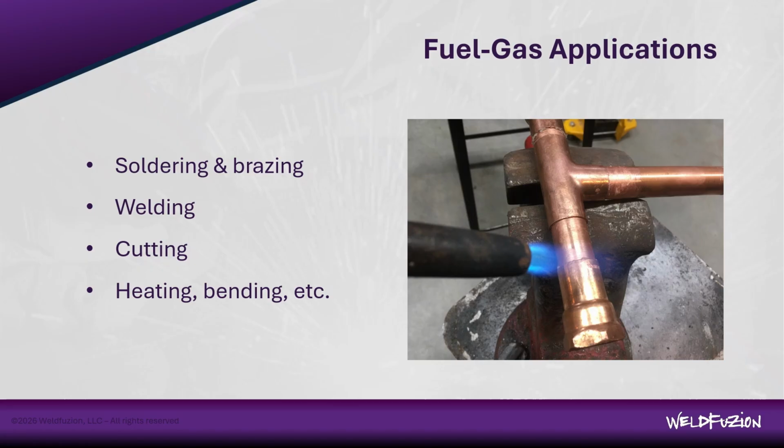Considering the open flame and the use of flammable compressed gases, that makes the process highly portable and utility independent, right? We don't need power to be able to do oxy-fuel anywhere. But in terms of operation, and considering those aspects, that also brings up a number of safety hazards, right? We're working with an open flame and combustible gases that are parked right next to an accelerant, which is the oxygen.